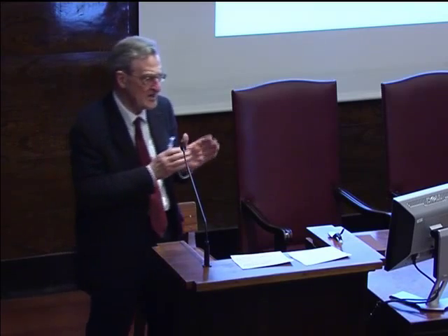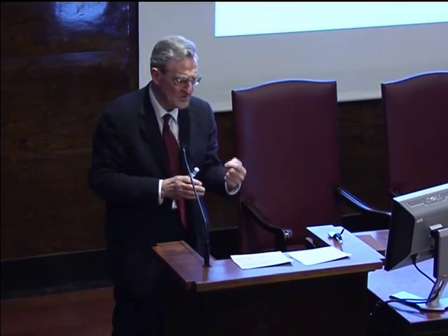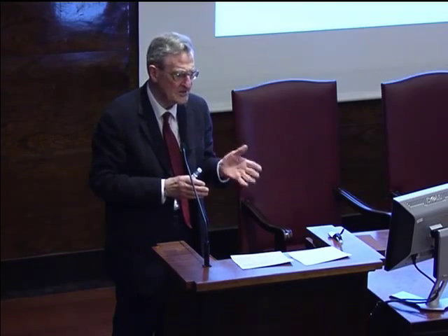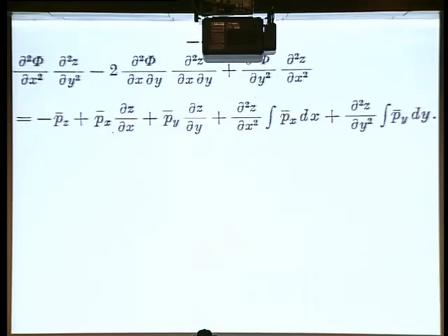That is, the cracking in the dome has already divided it into separate portions so that we've only got forces coming down the meridian. So we are defining the stress resultant system. We are defining, in fact, this function phi, which gives us the stresses. We can then solve this equation to give us the z, the shape of the structure which would correspond to that assumption. Right, so we're dividing the structure, no hoop forces.